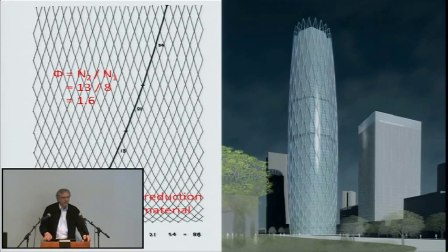The reason why it's important is because these mathematics, I think, can be learned from, and perhaps we think of them in our structures. So tall buildings, the idea of bracing systems that perhaps mimic the Fibonacci sequence. And the idea is that these systems, in this case, resist only lateral loads, not vertical load, not gravity load. Gravity load, we talked about that earlier, in systems that you could have dual systems where one system is taking the weight and the other system is taking the earthquake or the wind. And what we found was this change in geometry, this flattening of the frame and the density of the frame actually resulted in a much more efficient structure.